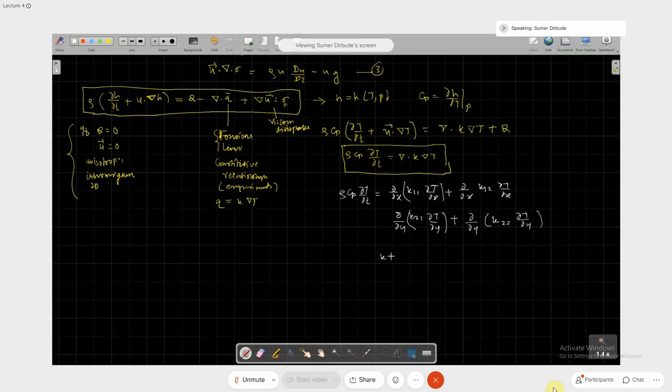You got this? So K is nothing but a matrix, K11, K12, K21, K22. So you do not have K as a single value, so you have to write this expression. If the material is isotropic, homogeneous and 2D, then K becomes constant. So del x K becomes constant, so that only one K will be there, and this K12 and K21 will be zero terms.